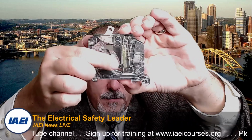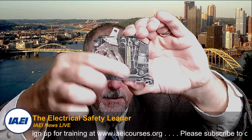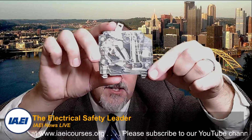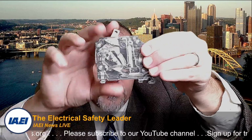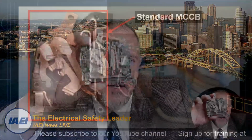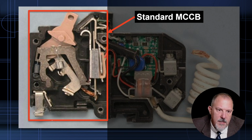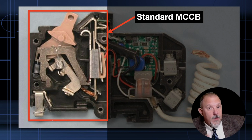Over here is my bimetal. This connects to the bus. This connects to the outside. This is where my load terminal is. This is where my bus connection is. So it's the same deal as over here on this image. It's a standard thermomagnetic device. It has to pass all of the requirements of UL 489.